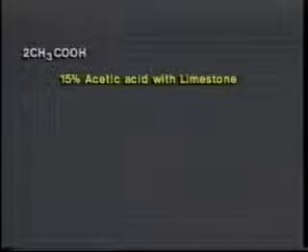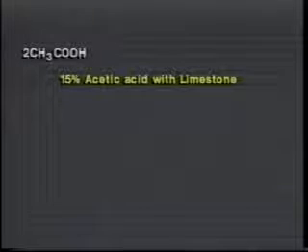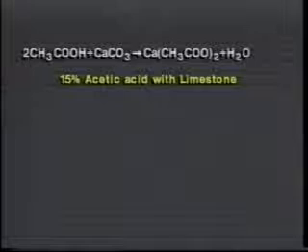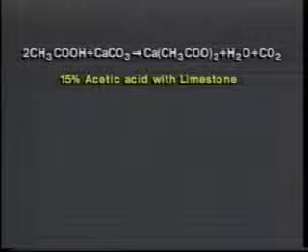Two organic acids that are used in the oil field are acetic and formic acids. Acetic acid is used during perforating because of the often lengthy periods when the acid remains in contact with the casing. Acetic acid can be used effectively in carbonate reservoirs. However, on a cost basis of carbonate dissolved per dollar of acid, HCl or formic acid is more economical. Acetic acid is most commonly used in limestone reservoirs and produces calcium acetate, water, and carbon dioxide.